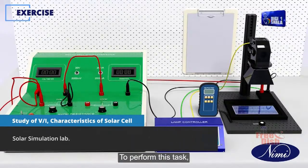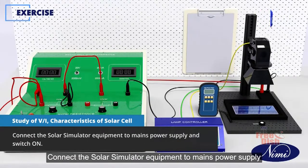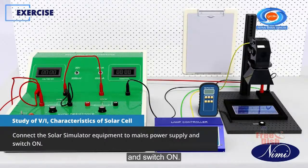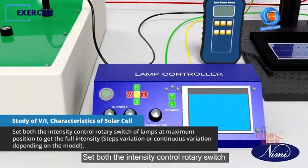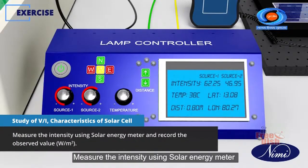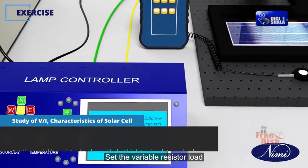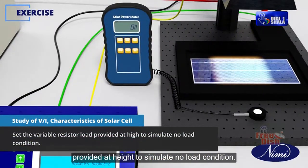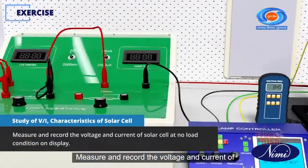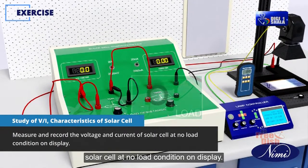To perform this task, you need a solar simulation lab. Connect the solar simulator equipment to mains power supply and switch on. Set both the intensity control rotary switch of lamps at maximum position to get the full intensity. Measure the intensity using solar energy meter and record the observed value. Set the variable resistor load provided at high to simulate no load condition. Measure and record the voltage and current of solar cell at no load condition on display.